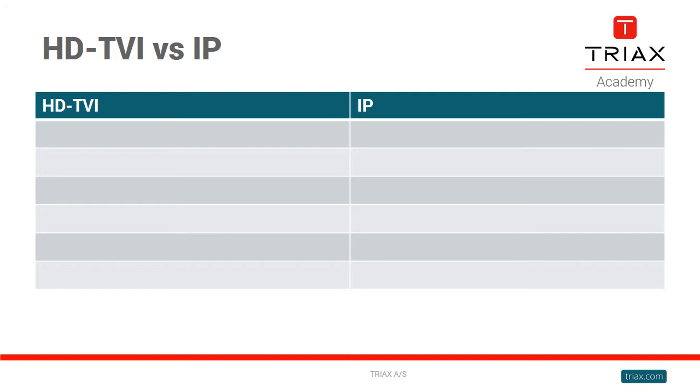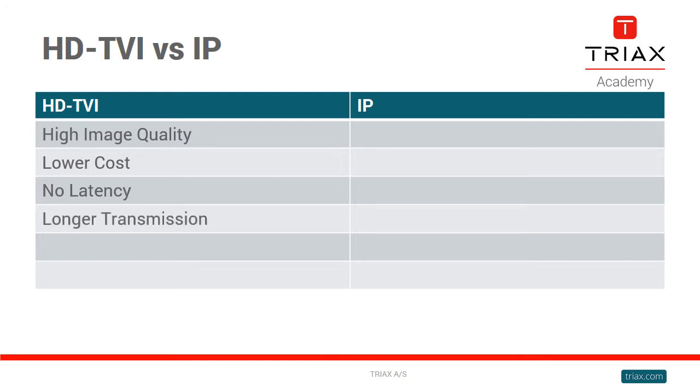HDTVI is an abbreviation for High Definition Transport Video Interface. HDTVI delivers reliable HD up to 1080p, without quality loss. It employs the same installation method, cables and connectors as traditional analog CCTV, reusing the existing coax installation. Monitor live video without time lag or latency. Transmit HD video up to 300 meters over RG59 cabling, making it the ideal HD format for long-distance cable runs.